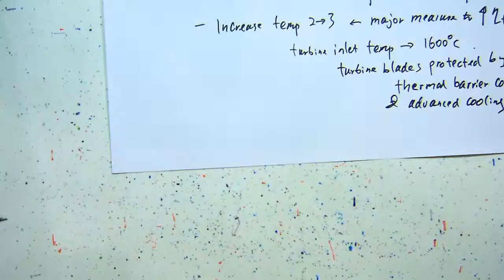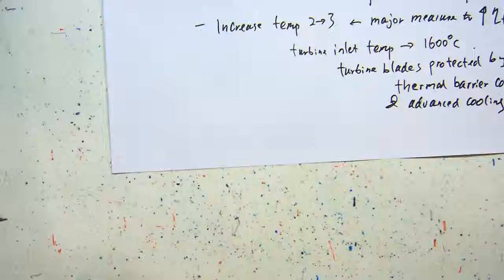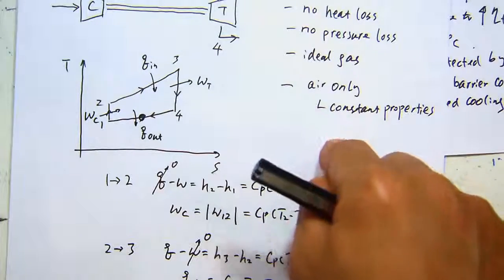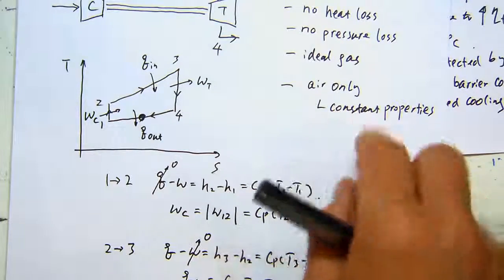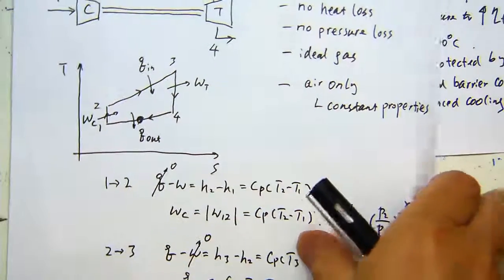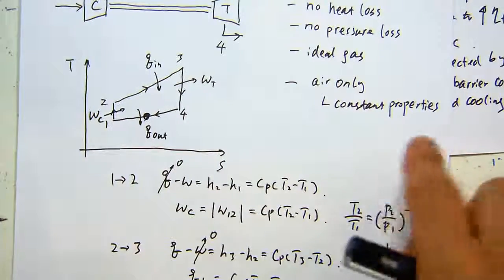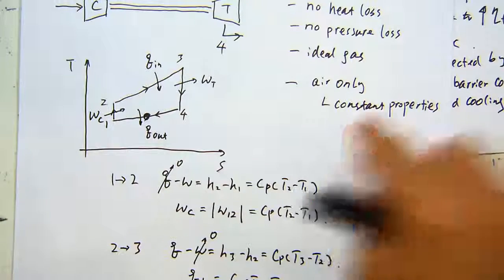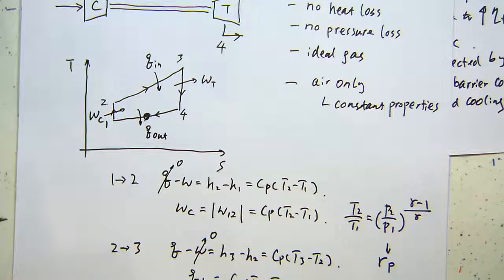In terms of the number, you can consider that the ideal cycle cannot be more efficient than the Carnot cycle, right? Because this cycle, the Brayton cycle, is not a Carnot cycle. It cannot be more efficient than a Carnot cycle. So that's its limit. And then you account for the different sources of non-ideal conditions, then you can get the actual thermal efficiency. For a typical Brayton cycle, I would say in reality its efficiency would be no more than 30%.